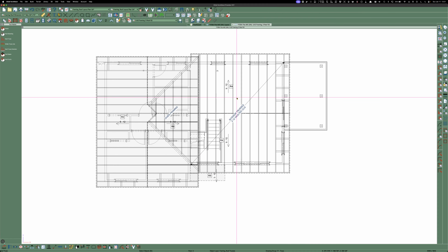And then the rest of these trusses will sit on top, or you'll run like a 2x8 or 2x10 ridge, and then you'll put 2x12s flat on the plywood, and then you'll rafter down. That's the other option. All of this is generated by the truss manufacturer, and you have to follow their instructions.